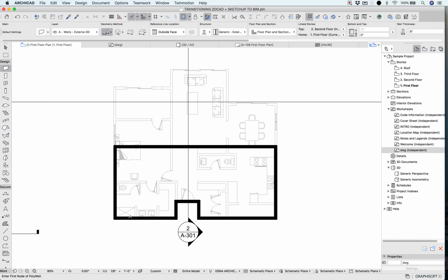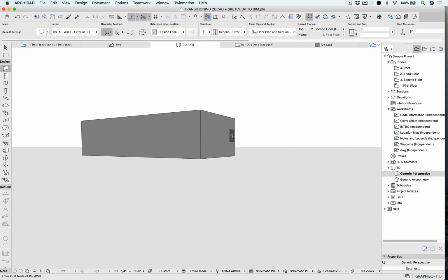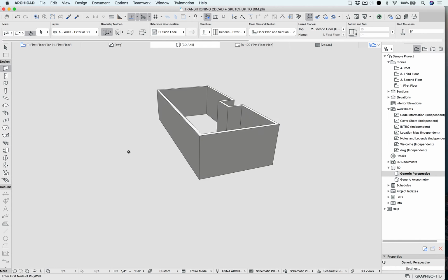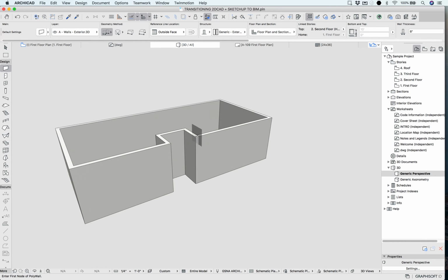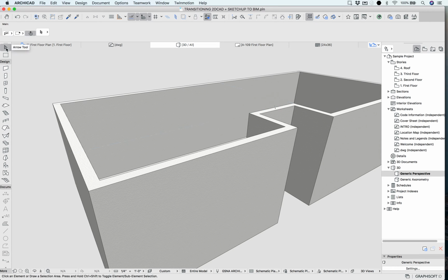So right away, just these basic walls, if I can see them here, I just capped it off for the sake of just the example, but it always appears in 3D, which the shortcut is F3, and we can return into our 3D window. So at all times we're developing, we can draw in any of these environments. I'm also going to talk about massing, kind of your SketchUp workflow. But one thing, if you do use these, is that this is what is called a generic wall.